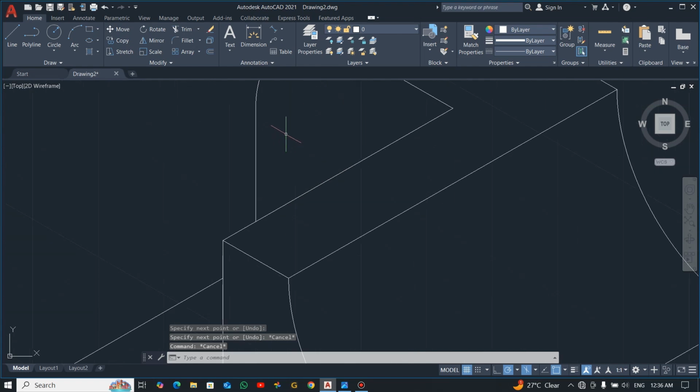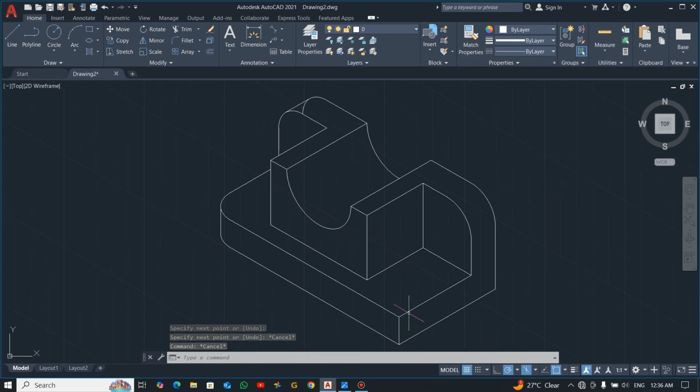Okay, so we are almost done. Remaining this side, the same procedure. Let's use the line command now. From here, drag 15 and go inside also 15. Okay, so this becomes the center. Pick ellipse, click here. Sorry, you need to change to ISO top, so F5, ellipse again, then drag to the quadrant. Now trim.